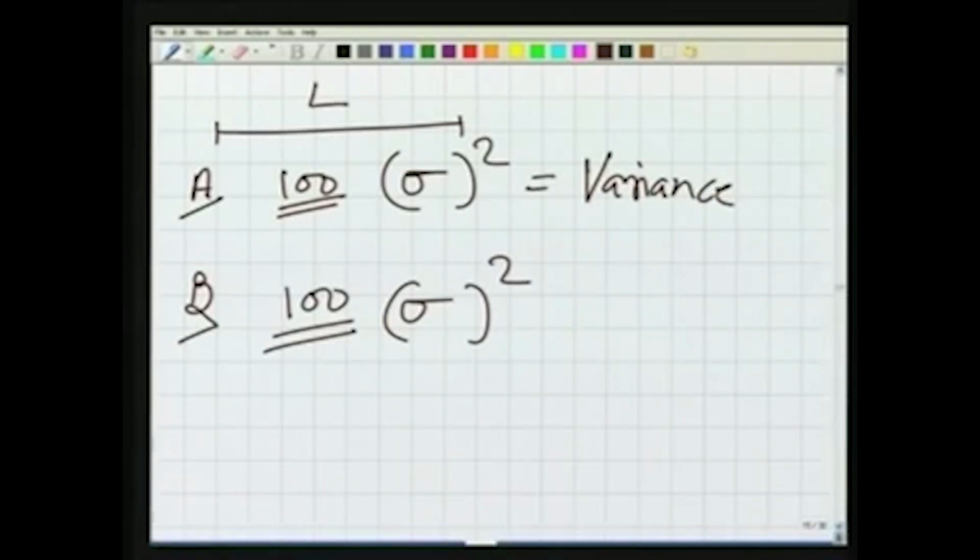Now, why are we giving the weight as per the sigma? What is the reason? Because it gives us the closeness of the observations. An observer who is more sincere, who is working very well, where the sources of errors in the field are less, the chances are all the observations will be very close to each other. So if the observations are closer, we want to give them more weight.